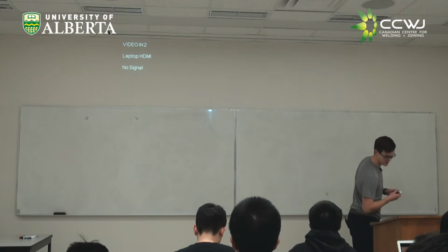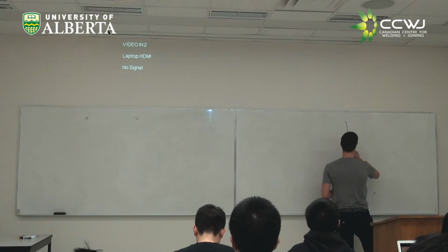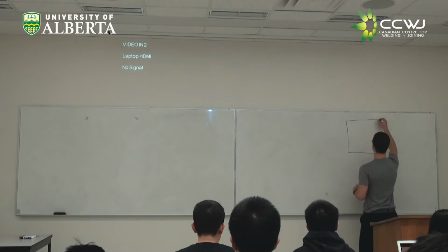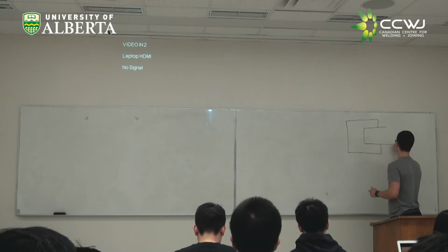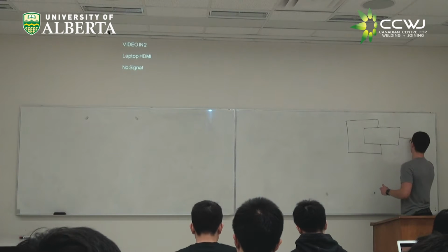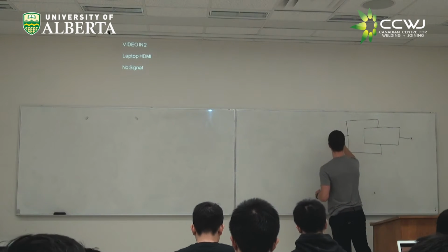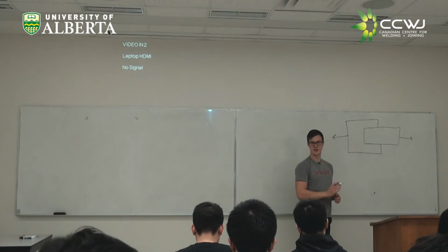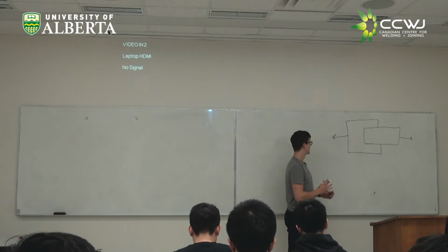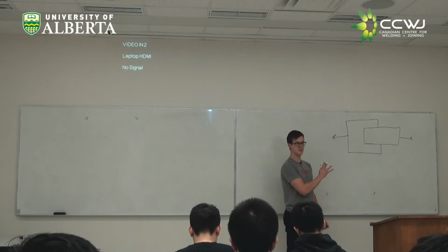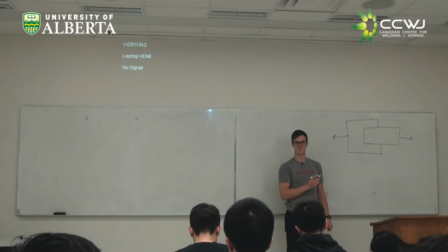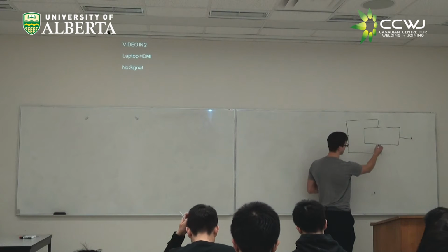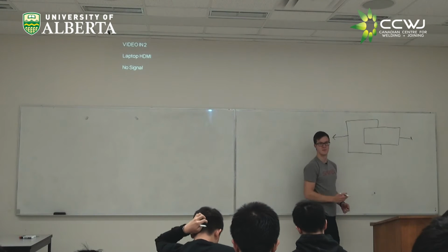So we have what ends up being a pretty standard situation for these type of problems. We're going to have a nice schematic like this where we're loading in shear. Now, we talked about loading in tension, loading in shear. Hopefully you guys picked up on most of what we talk about here when we're talking about fillet welds ends up being shear loading. So if we're loading this way and we're welding around here, that's a shear load.